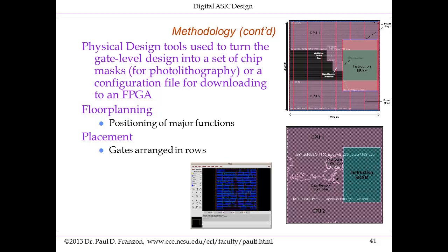After producing a netlist, we then want to turn to physical design. There's 2 major steps here, floor planning and placement followed by routing. In the floor planning phase, a designer might input a floor plan such as on the top right. This gives the general idea of where each function is going to be. In this example, we have a dual processor unit that we designed as part of a 3D project that's integrated with a cache.